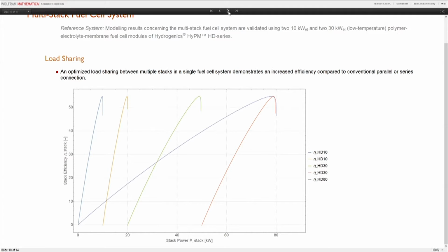And so this immediately showed the idea that we should try to use it. The idea was to combine these 4 fuel cells in a way that when you draw power out of the system, at the beginning only one of the systems is loaded up to a certain amount, and then some passive components like diodes or stuff like this take one of the others into account, so that we get a curve which follows roughly such a shape. And it's easy to see that especially in very low areas of load, we get a very high efficiency.